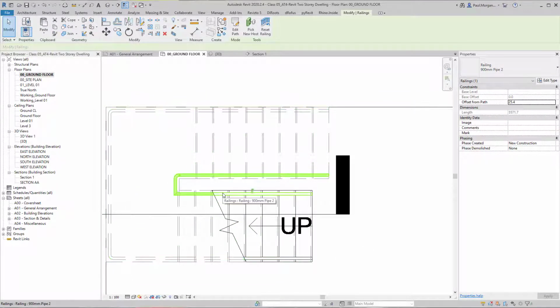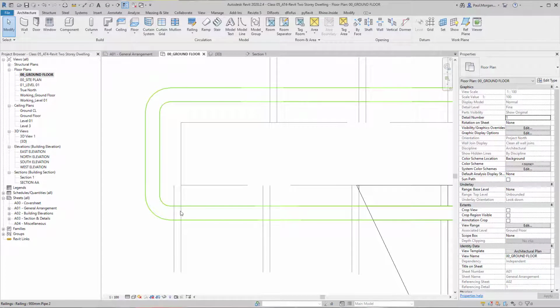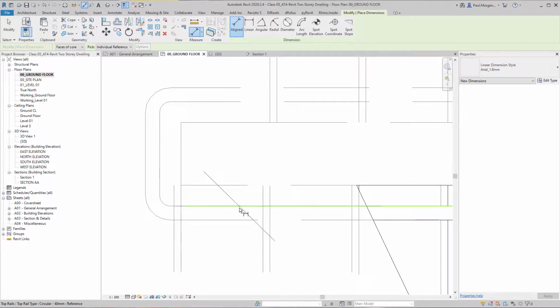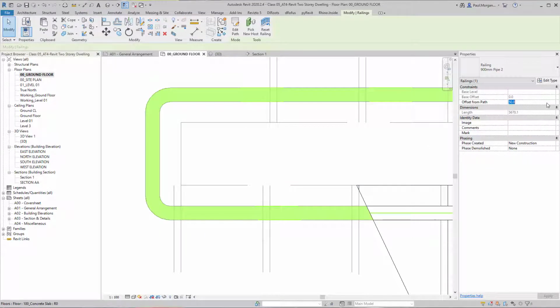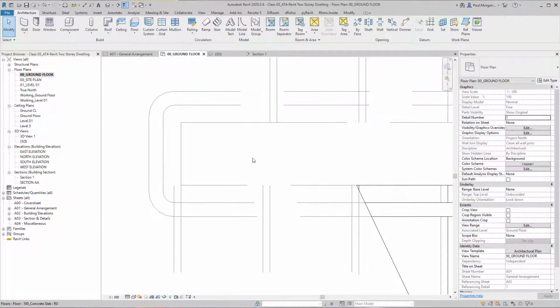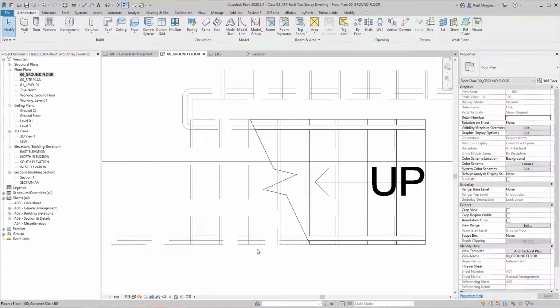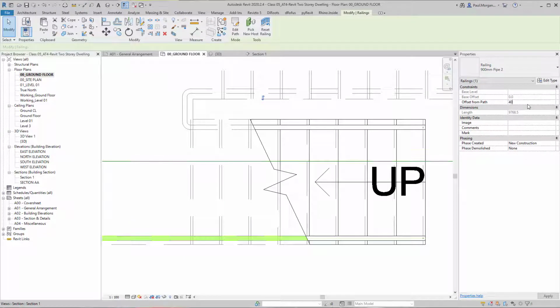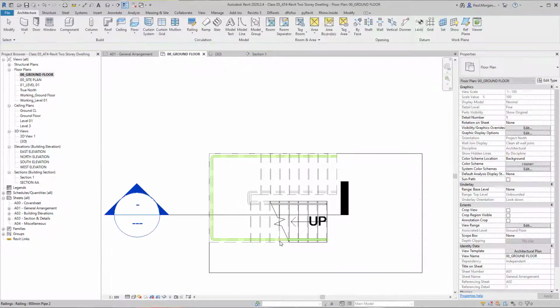Particularly I'll do this one here, and you can see the offset from the path is only 25 mil. So what I'm going to do is change that to 50 mil. The pipe grows, and you'll see now because the handrail has come out, it can now fillet it. So let's just double check that distance. That's 60, so I need to make a quick adjustment. That will actually be 40. Beautiful, 50 mil offset. And then I'll do the same thing for this pipe as well. So 40 mil. And now I've got a nice 50 mil gap for my hand between there.